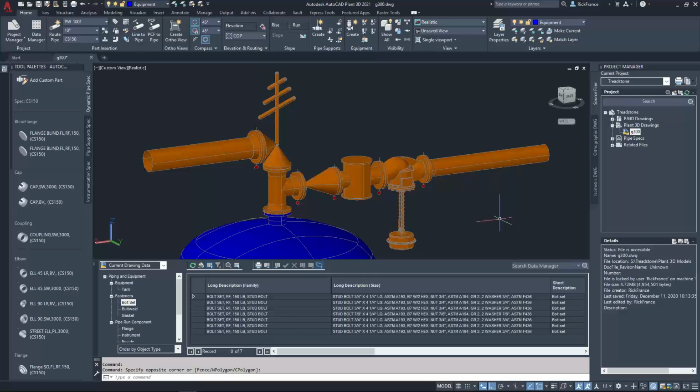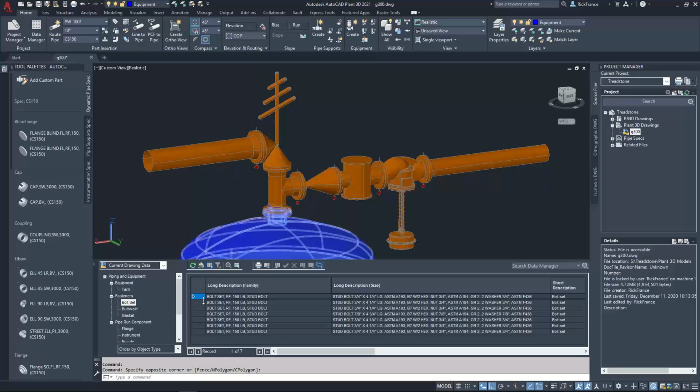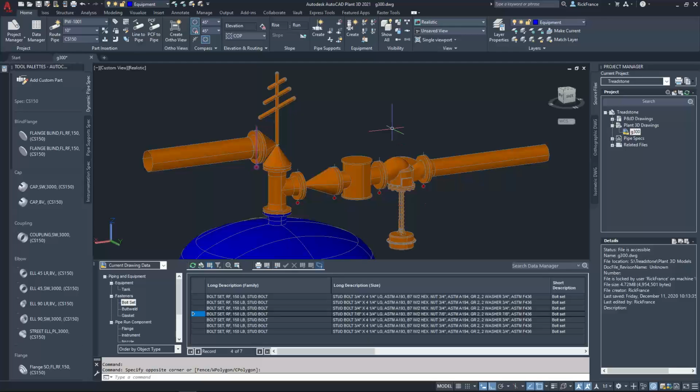So those are just existing components, but all the bolts right now that you see on the screen are using out-of-the-box bolts. And you can see here, this is an 8-inch pipe, this is a 10-inch. You can see here the 3/4 inch bolts, which are the ones on the 8-inch flanges, are all 4 1/4. There's a 7/8 inch bolt here. That is the 10-inch bolt there. And then you have some others here that are, again, out of the box, so they're all 4 1/4 inch long. So what we're going to be doing here is basically showing you how to manipulate those sizes both manually and automatically as I work through this process.